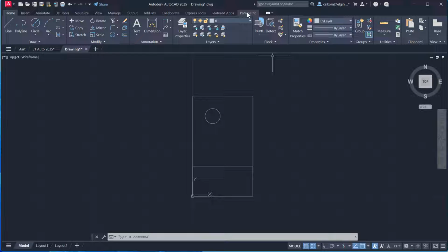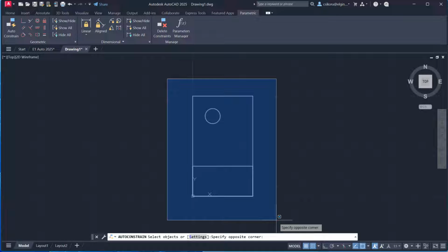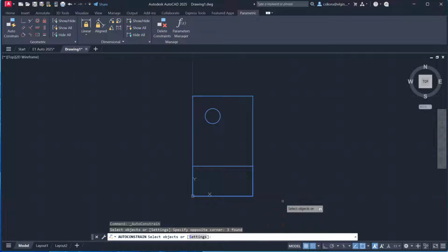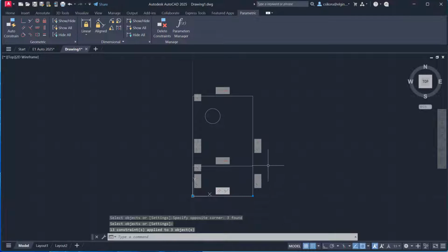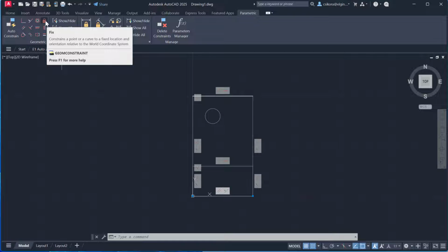Now, parametrics are halfway inside this software. Basically, you could make a parametric sketch, and it enables you to change it very easily with dimensions. So select parametric. Now you'll see, since this is to size, all we have to do is click on auto constrain, click once up here, release it, and then move your pointer to select around the geometry you want. Click again and hit enter. And it will add all these little values. Basically these are common elements of geometry, like parallelism, perpendicularity, horizontal. And one that we're going to add manually is the lock. This is basically fix or anchor.